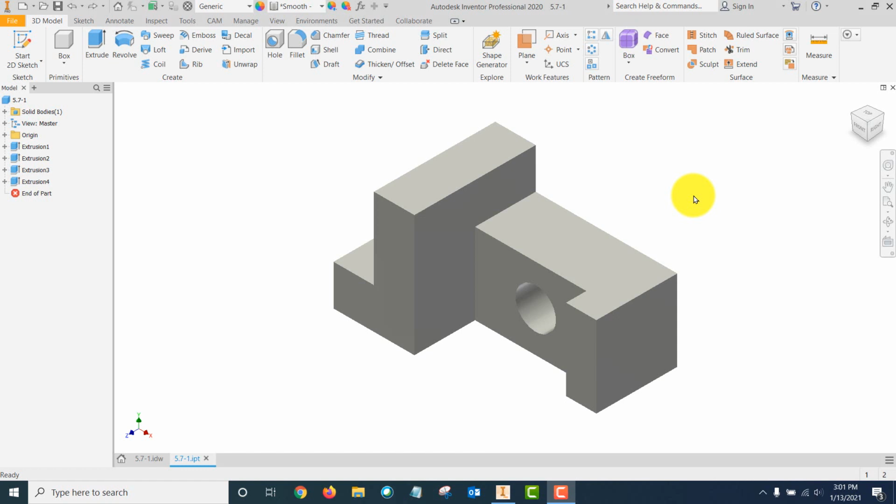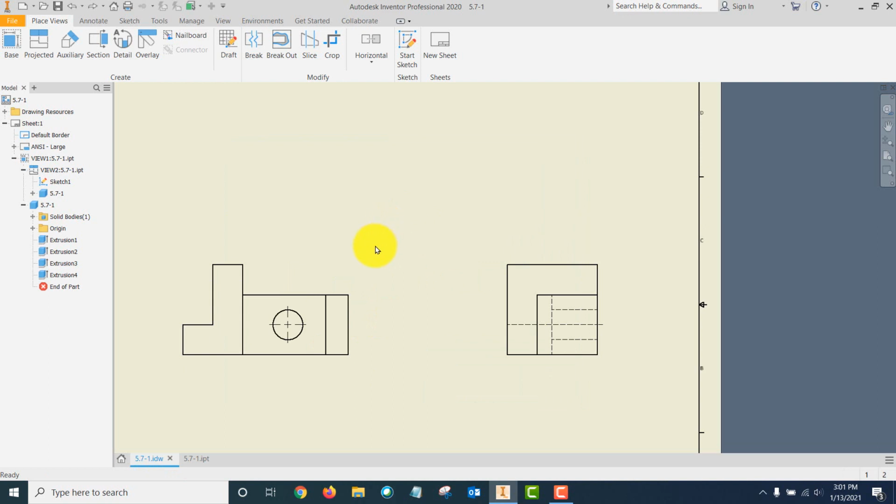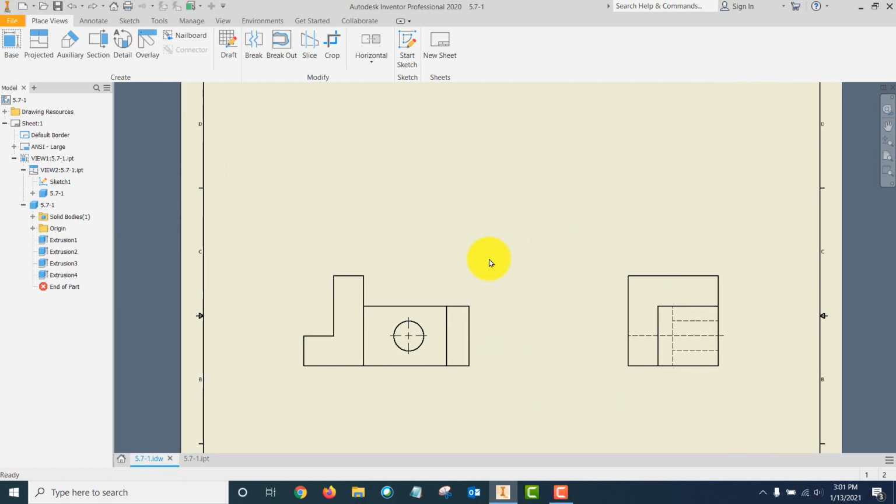Okay, let's look at drawing 6.7-1 in the new edition of the textbook. And here's an isometric view of the completed object. But let's look at the drawing. Now, granted, it's a sketch in the textbook, and you're using the grid lines to determine your sizes. But what I want to talk about is hidden lines and feature lines.